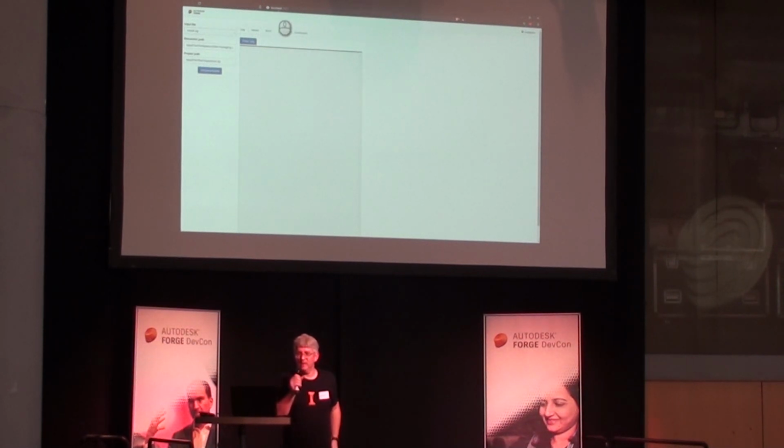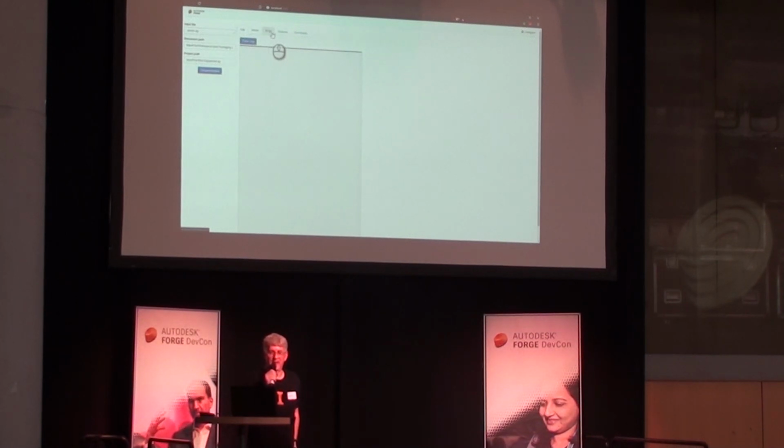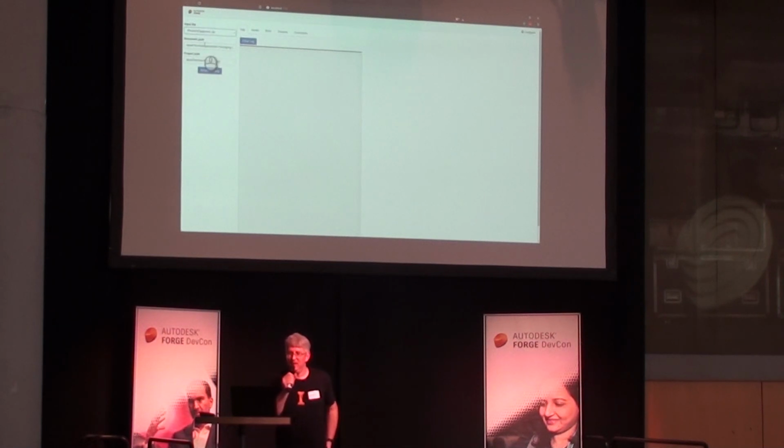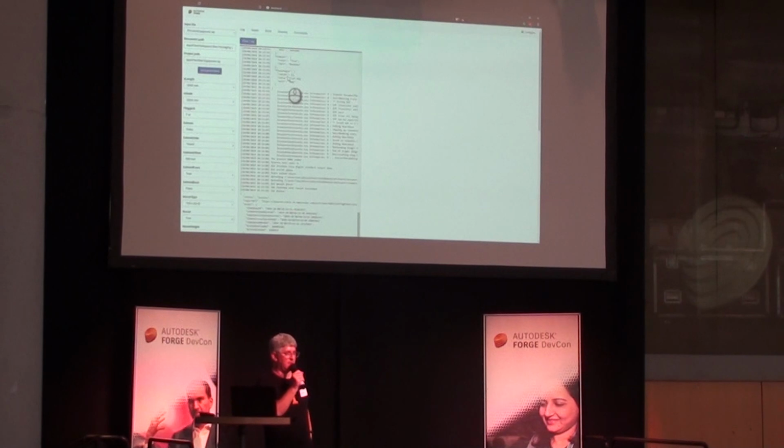Okay, so you'll notice here you have an input file dropdown, a document path, and a project path. As long as you upload an assembly that's set up the same way as this, it should really work on any. So I'm going to click my processing equipment zip file, which is a zip of the assembly, specify my top level assembly file, and specify the project. It goes off and runs a work item. I get back a unique ID, and 38 seconds or so later, I come back with a result and all my user parameters.